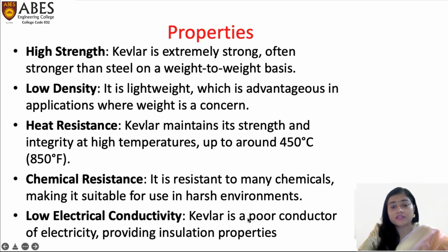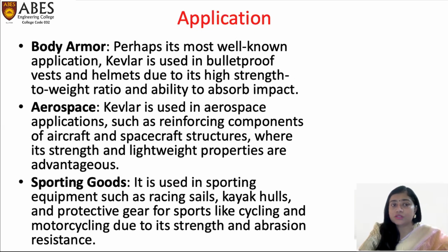It's a poor conductor of electricity, providing insulation properties, and this is why it is also known as space suit material. It is used in body armors, with well-known applications in bulletproof vests and helmets due to its high strength-to-weight ratio and ability to absorb impact. It is also used in aerospace applications such as reinforcing components of aircraft and space structures, where its strength and lightweight properties are advantageous. Also used in sporting equipment such as racing sails, kayak hulls, and protective gear for sports like cycling and motorcycling due to its strength and abrasion resistance.